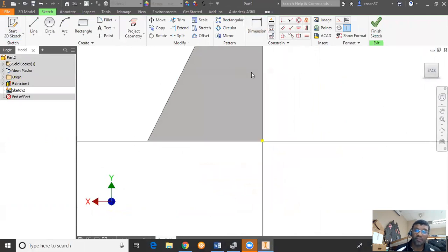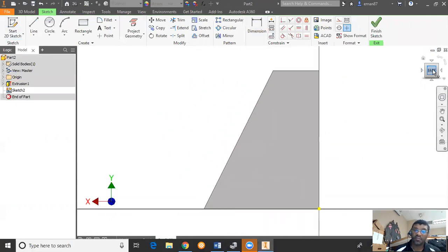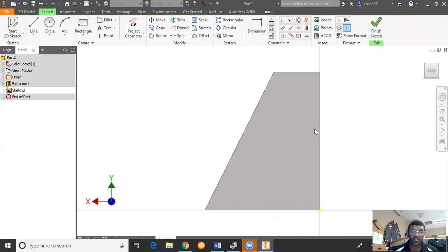It's zoomed out of view. I hit the word back. It'll zoom back, it'll do zoom back center. So now what I want to do is, I can do it 1 or 2 ways. I can do a rectangle, or I can do a line. I want to do a rectangle on this one. So I click the center, and I'll just open and stretch my cursor.